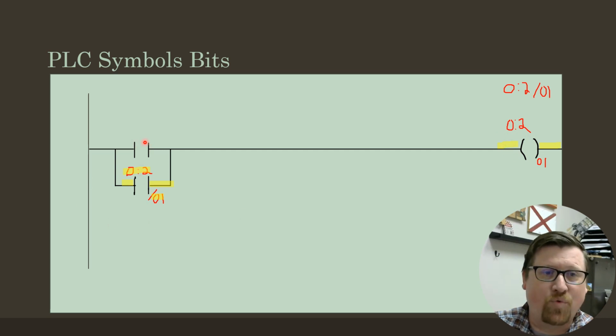And so then when I release the push button that is controlling this set of contacts, it will leave this one on, and I still have a path for, not so much electricity inside the program, but my information is true. This rung is true until someone stops it.